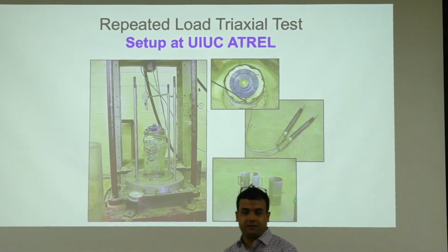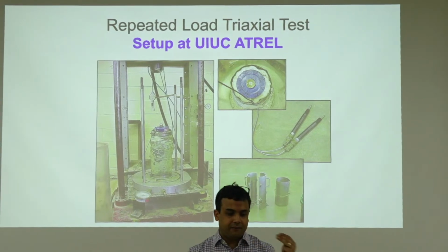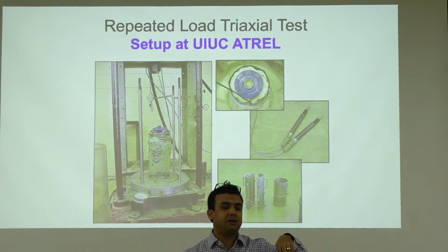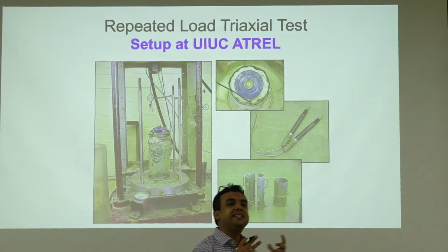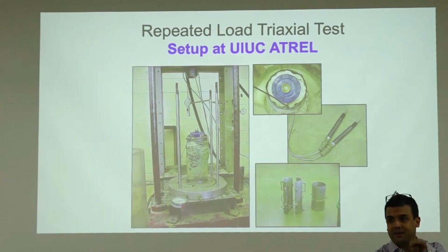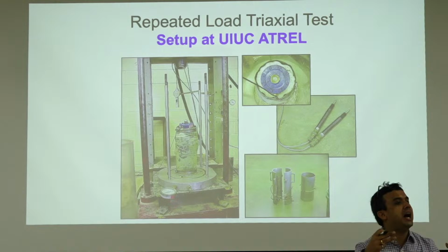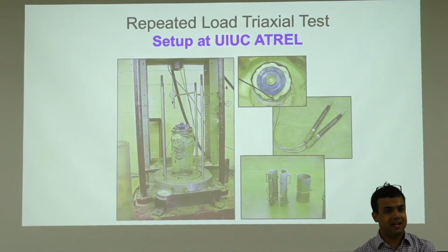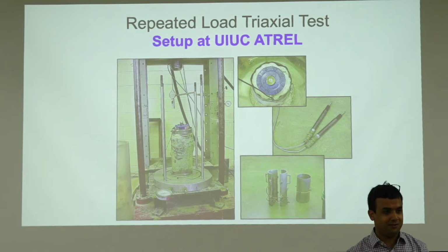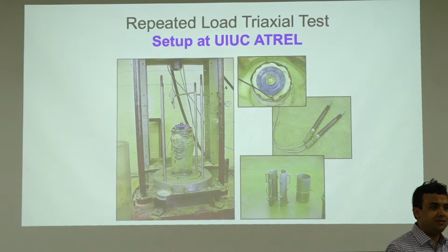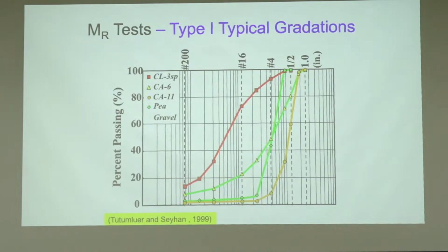Usually, by the way, if you look at the test specification or even your vendor equipment manual correctly, resilient modulus is a non-destructive test, right? It is at very small strain levels. So after resilient modulus, you can actually run a shear strength test on that same sample, as long as you don't have LVDTs mounted. If you don't have them, you can run the same shear strength test and you get 2 data points for one specimen. So this is after running the shear strength test.